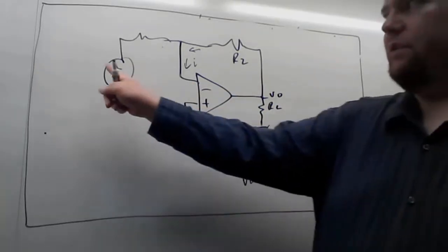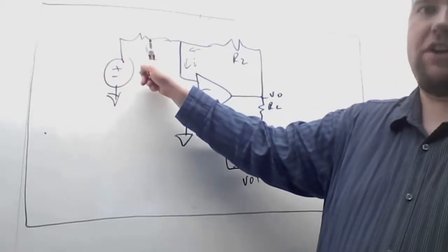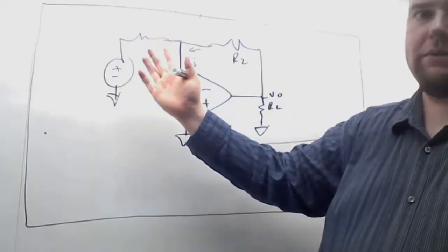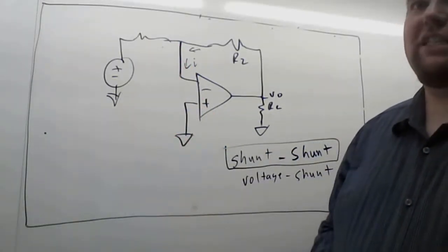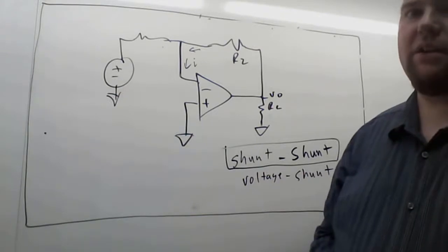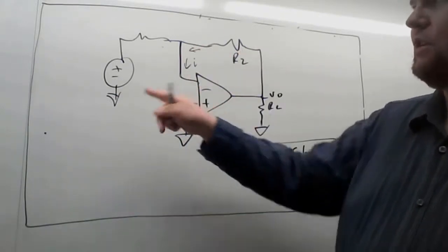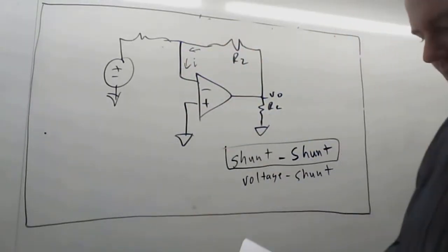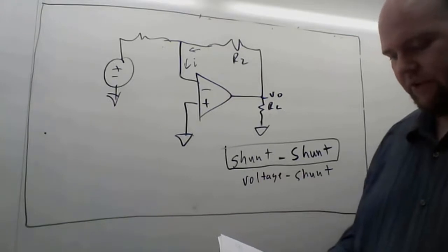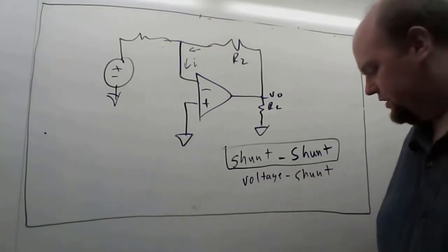So what we're doing really in this circuit configuration is we're generating a voltage which is getting converted by the resistor by Ohm's law, V equals IR. We're converting a voltage in series with a resistor into a current supply in parallel with a resistor. So we're really using this as a current supply, and we're using this current to combine with this current. Okay, so that's how we're combining them to get our 0 there. Okay, so let's look at a couple other circuit configurations.